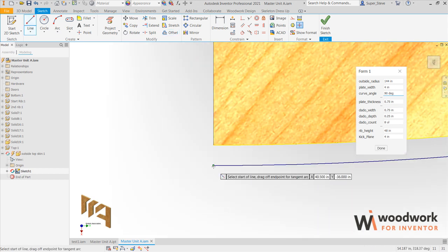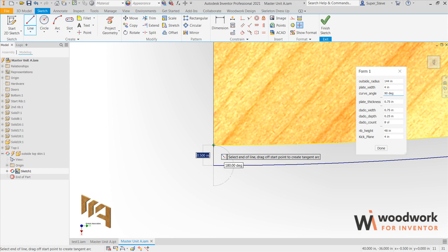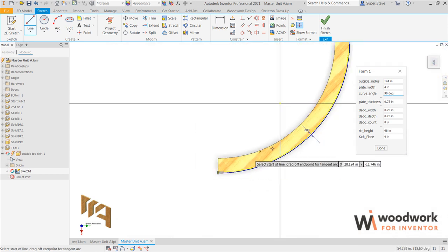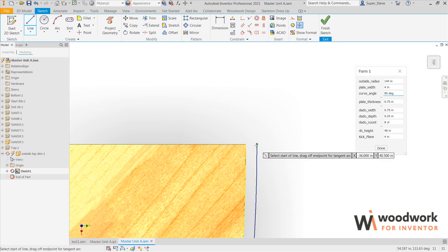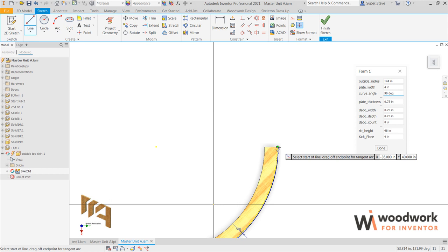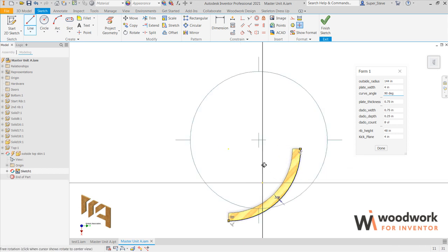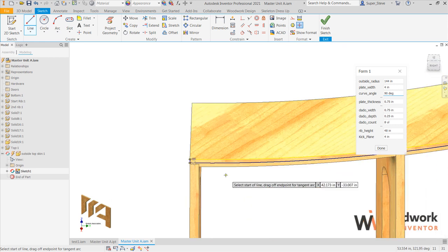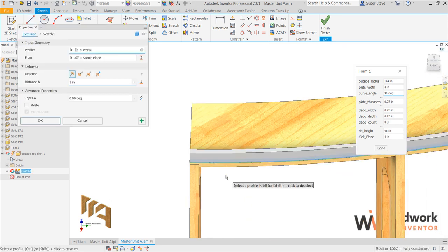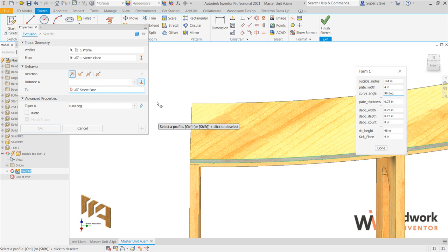And like a hatch pattern, I have to close the perimeters, okay? It has to be a closed loop. If it's not a closed loop, I'm not going to be able to extrude it. So again, quite simply, we're using the geometry that's there, and by using that, everything also will become parametric.